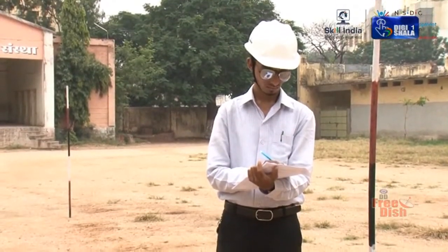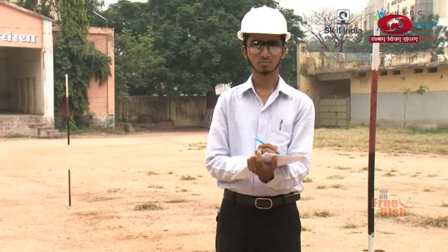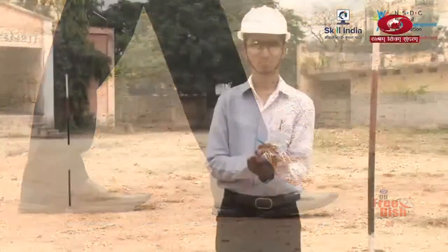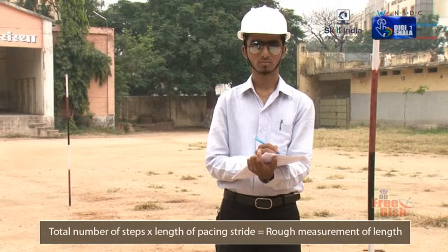He then multiplies the total number of steps that he has taken between the 2 points with the typical length of his pacing stride, which is already known to him. This product of the number of steps and the length of his pacing stride is the rough measurement of the length between the 2 points.